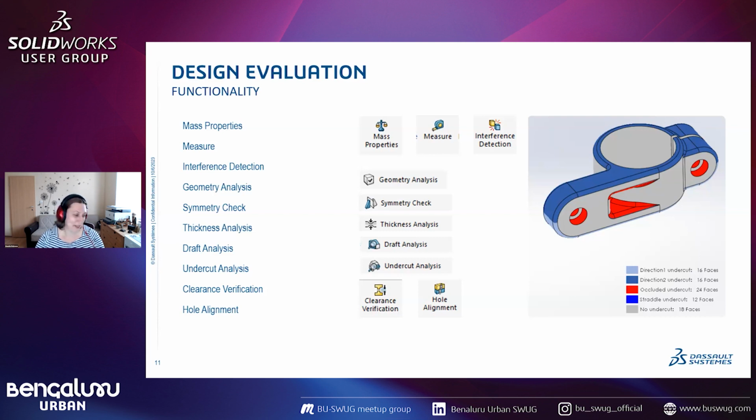And at the end, you see on the printer one failed print, and it's like, oh, I forgot to check this again. You go to SolidWorks, you run the thickness analysis, and you see, yes, you have a too thin wall. And that's why that's also a great tool, and you need it. I mean, it's a must check all the time.